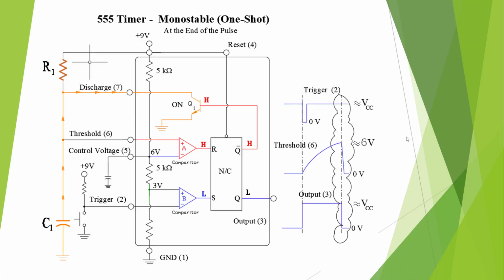Here's the end of the pulse diagram of the 555 monostable. Once we charge this, which we've done already, it's going to discharge once it hits this 2/3 point. We're going to discharge this capacitor through our transistor to ground, and it is going to turn that device off, go down to the 1/3 position, and wait to be retriggered.